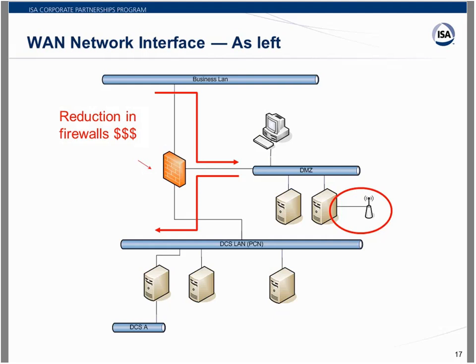A firewall is an expensive solution to a problem. They have to be maintained. There are some great other products, and I'll bring some of those up now, like data diodes or pre-configured firewalls for automation that might actually do better than a generic firewall. The other part, as I talked about before, is that SMS device shown here by the radio. There probably needs to be a constant audit, or even constant monitoring, where you would put something on that PC and say, if I ever see inbound traffic from this port, I'm going to send an alarm, because that's never supposed to happen. That's part of that monitoring concept, which is very far down in a typical cybersecurity program.